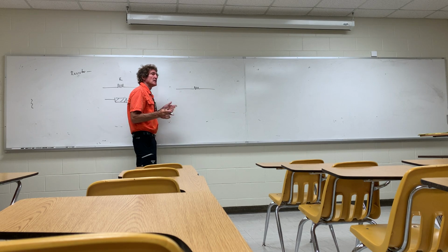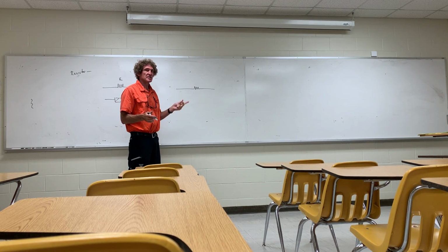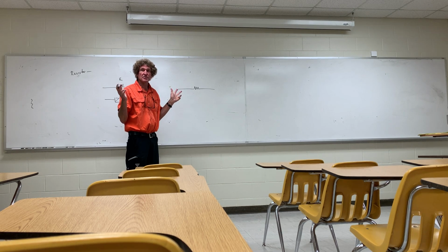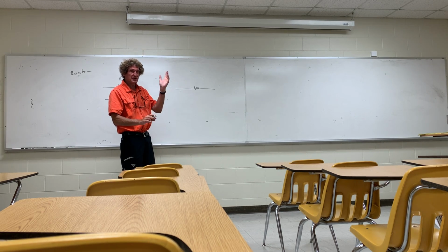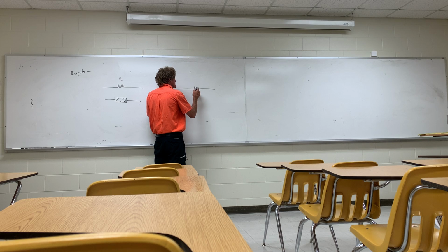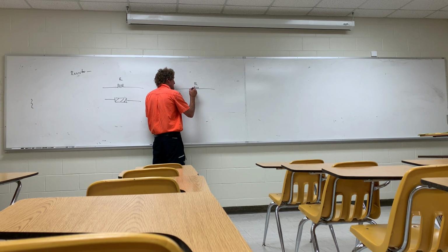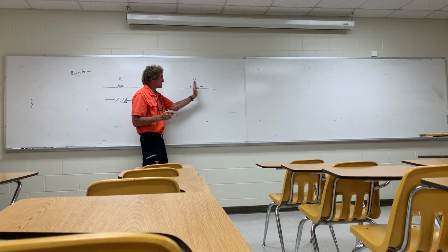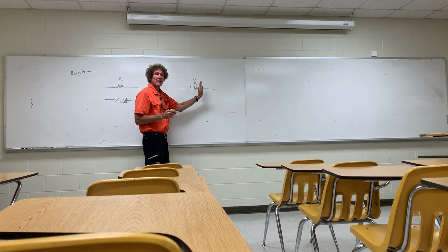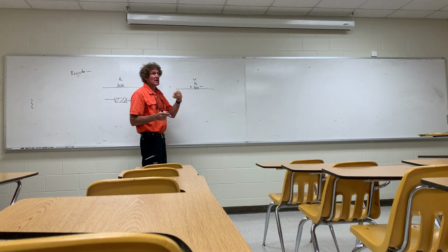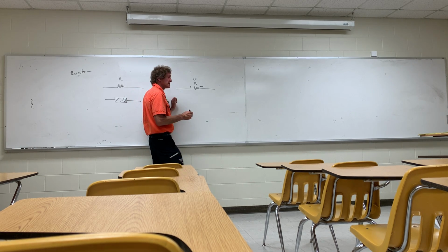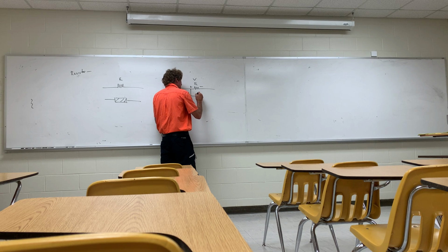Now all elements, either inductors, capacitors, or resistors, at low frequency look like what they're supposed to. They look like the resistance, or the capacitance, or the inductance at low frequencies. But as frequencies go up, things change. So when you have a resistor R, that's what it looks like at low frequencies. But then something happens, because you're going to develop a voltage across there. You all follow me on this? Anytime you have a difference in voltage between 2 points, you have charge buildup, positive and negative charge. When you have that, you have effective capacitive energy.